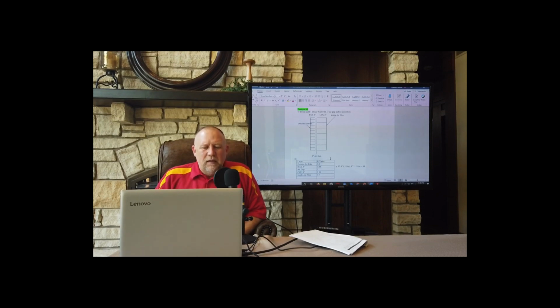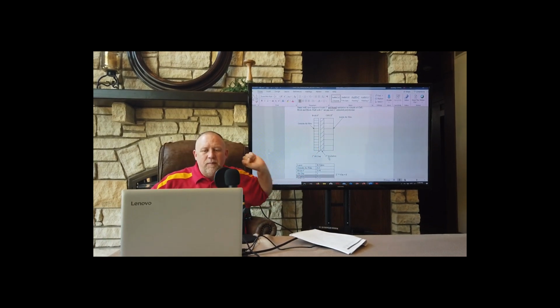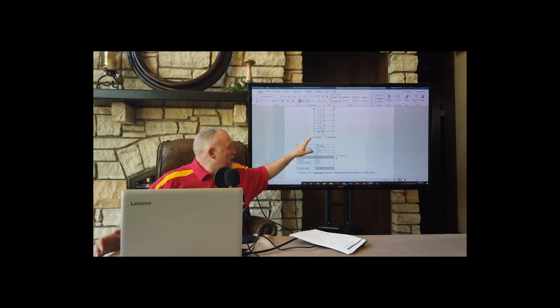So you might be talking about an older building where the R value for the air gap and the air films is fairly significant. Now, on a modern building, if we go down to the next example where we've added a 2-inch rigid insulation in the middle, 2 inches of expanded polystyrene, it's the exact same wall, the exact same calculation.